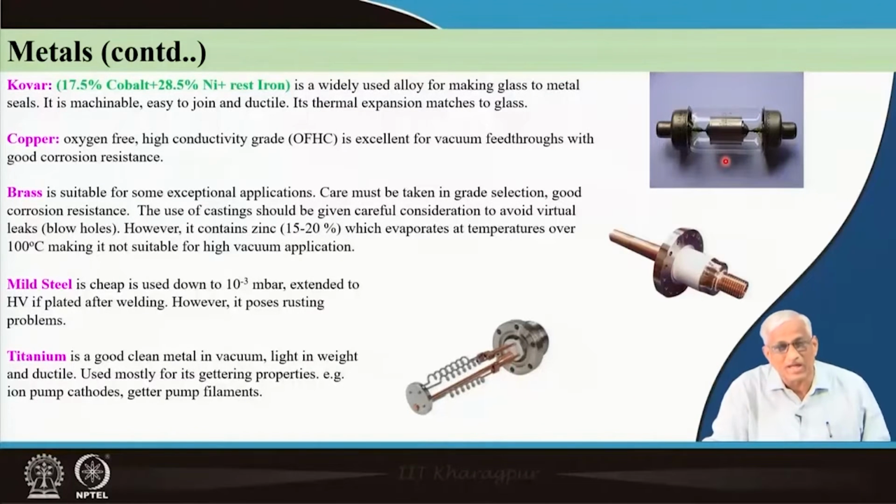Most high power electronic applications still have valve based electronics, triodes, diodes etc. In such places you will have metal-to-glass joining, and that is possible with Kovar because it has matching thermal expansion coefficients with the glass.